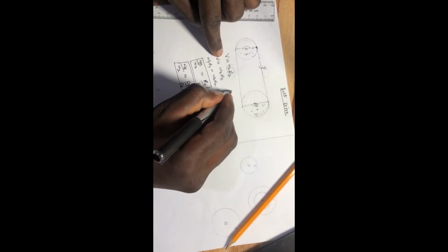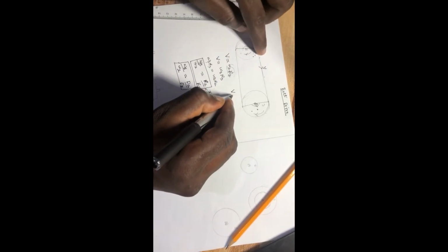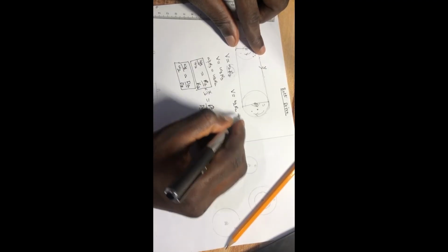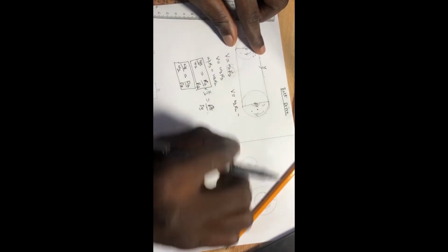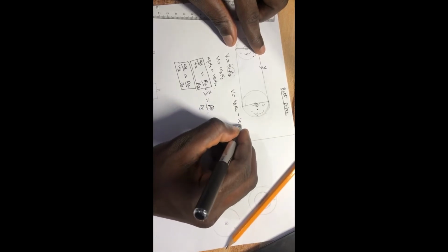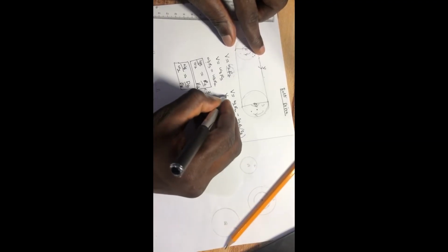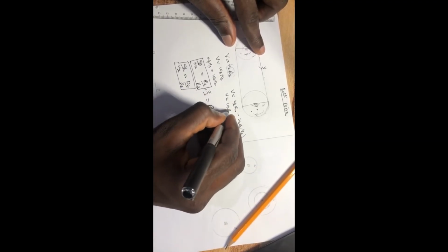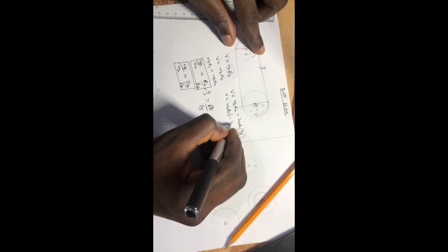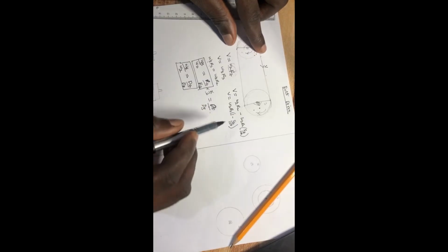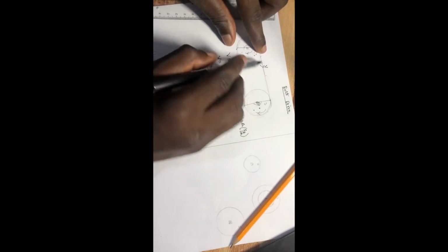So if that's the case, then the velocity that is reaching the belt will be equal to omega 2 R2 produced minus the component that goes into what? The slipping, which is omega 2 R2 times the slip percent. So let's say S2 on 100. Right, so this means the velocity is equal to omega 2 R2 into brackets 1 minus S2 on 100. Right, if that's the case, then this is the velocity that is reaching the belt.